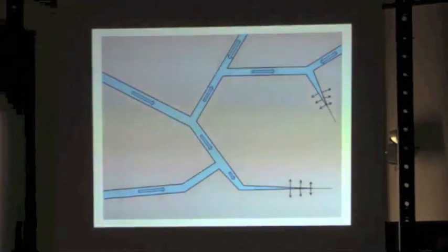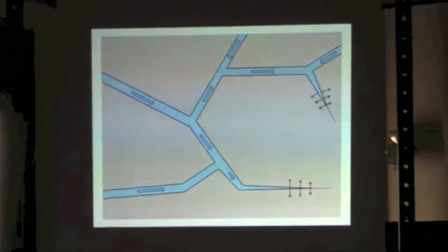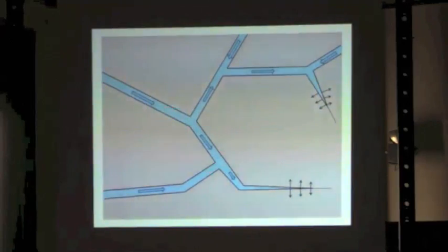So what we want to model is something like this: a 3D fracture network in a porous media, with fluid circulation in the cracks and fracture junctions, and we also want to focus on the mechanical part of the problem. I'm talking about the fracture propagation, also about the fracture competition, so the influence of the presence of one fracture close to another fracture, and also the problem of the fractures shutting down when the two walls of the fracture are in contact.